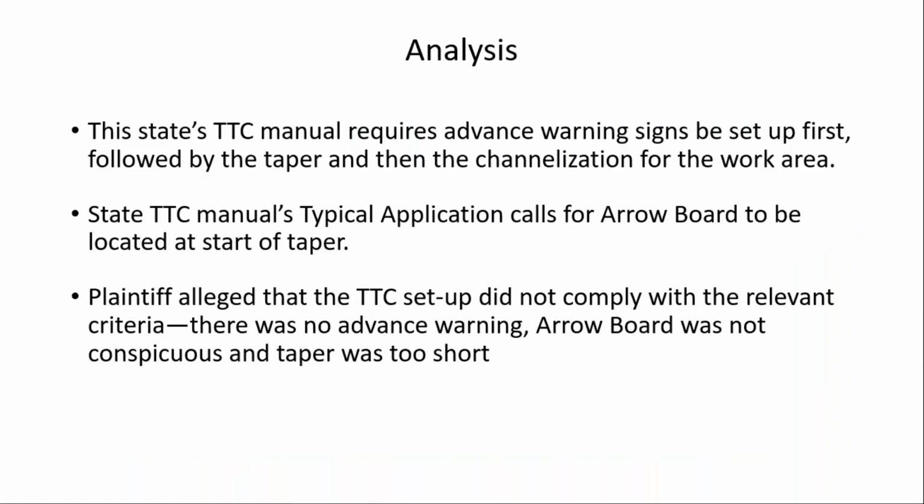The plaintiff's analysis was that this state's temporary traffic control manual requires advanced warning signs be set up first, and it appeared that in this case they were not, followed by the taper and then the channelization for the work area. So it sounded like this crew set this up backwards. They set up the taper and then the channelization for the work area, but they set up the advanced warning last, or actually it didn't get set up in this case. They were going to set it up last.